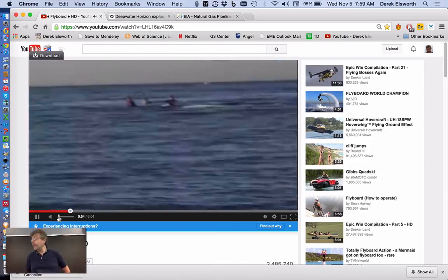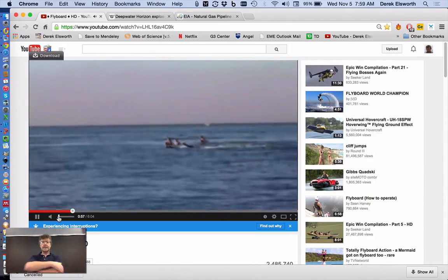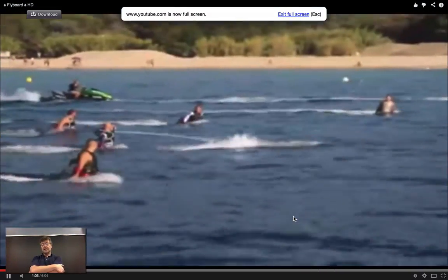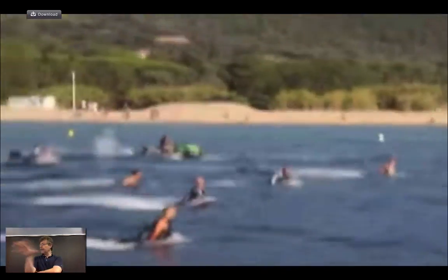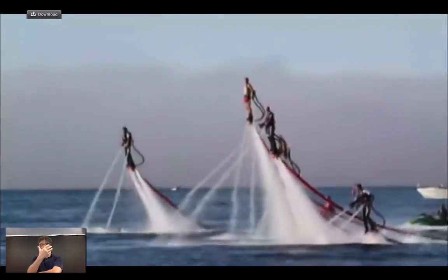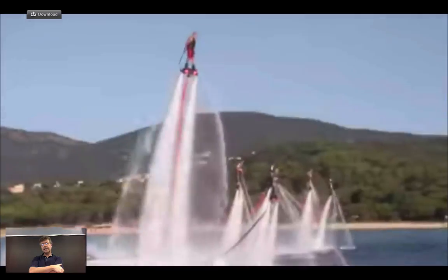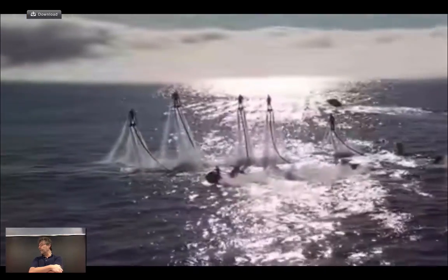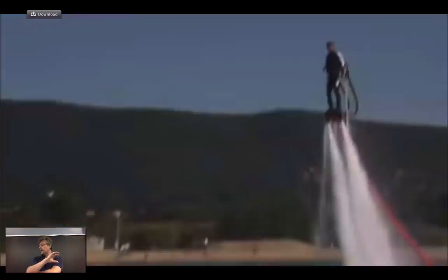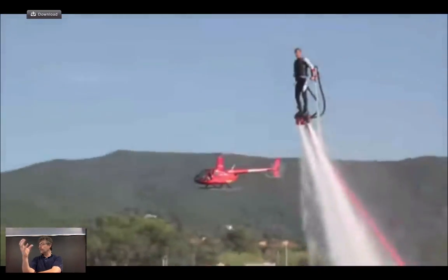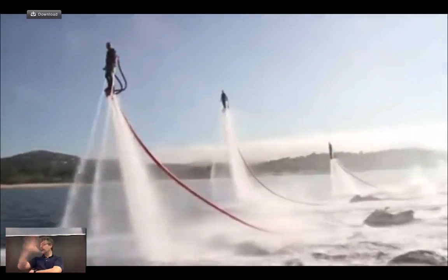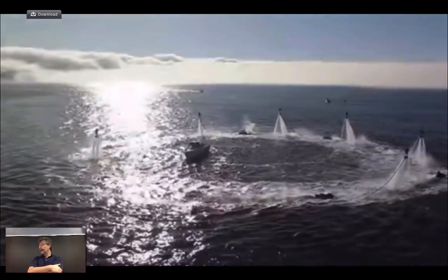So we've been talking about pipe flow, and we've made the point that pipe flow looks at this behavior between friction factor and Reynolds number. Friction factor is really a surrogate for an Euler number, a force, a pressure divided by rho v squared. And it's really not very much different from the behavior that we expect to see if you looked at flow instead of in a pipe, where you have this shear stress applied on the inside of the walls, which is the friction force which resists flow, to if you capped off the two ends of the pipe and you had air or water flowing past it and causing drag.